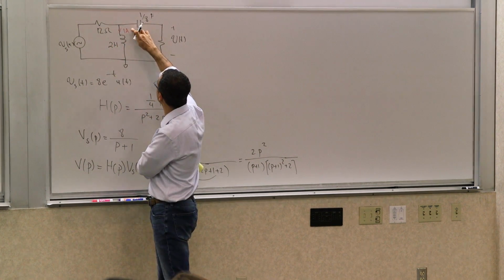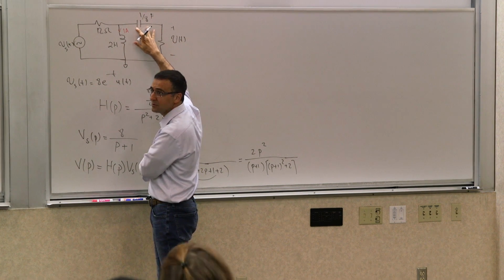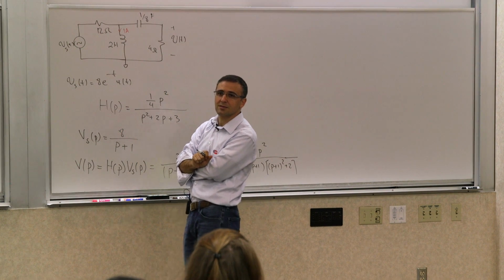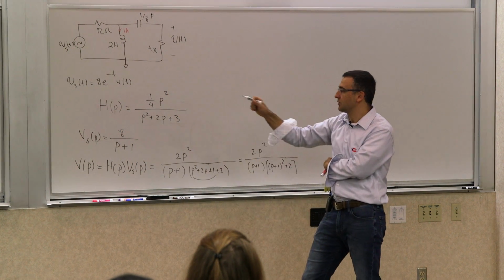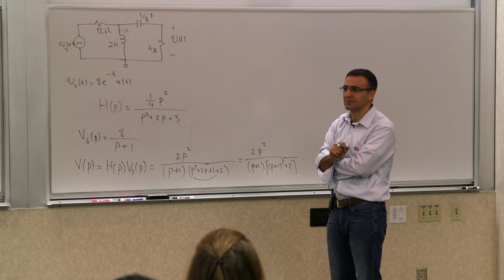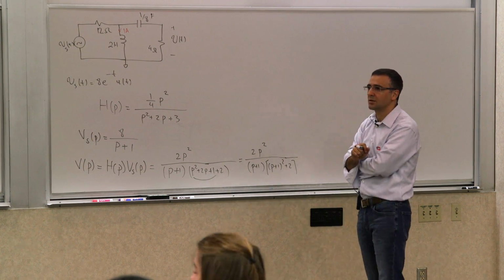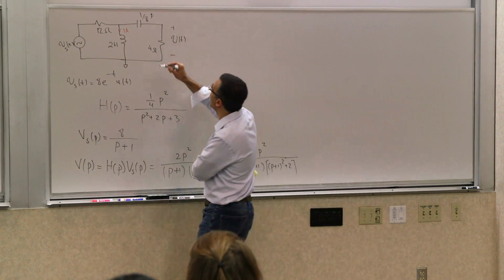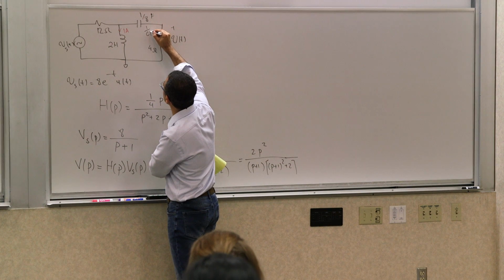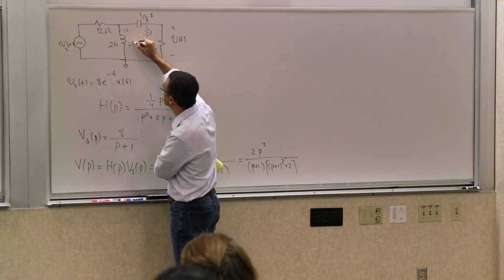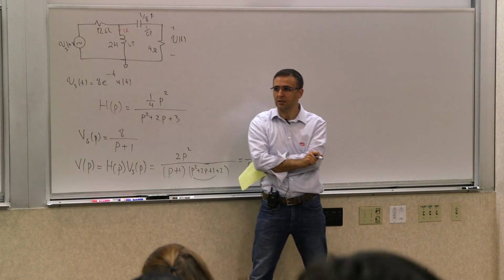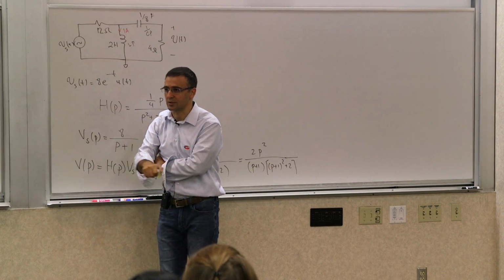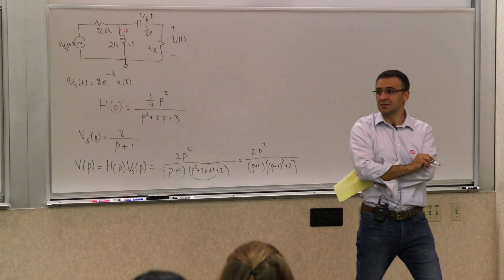Then from there, you do another voltage divider between this and that, which would be this resistance divided by this resistance plus the impedance of this capacitance. So if you do that calculation, you will get that. I didn't do it, I was just lazy, looking at the resistances but solving it down to the impedance seen by that. Exactly. So I treated this as 1 over Cp, and I treated it as Lp, and treated it like resistors. It's just the transfer function, the ratio of this voltage to that voltage if you had these 4 resistors, which we now call impedances.